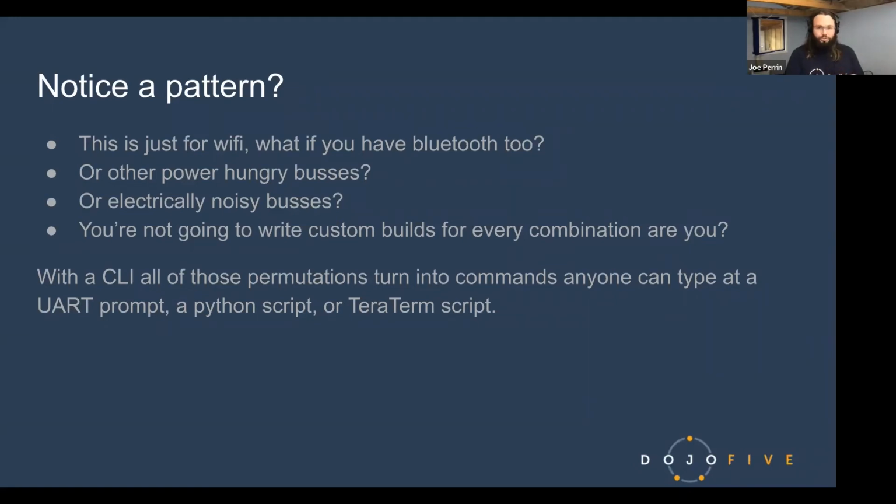If it's a separate Bluetooth transceiver, you can turn that on in max transmit. You can turn the GPS on and see if you've got coexistence issues, right? And when your systems guys are doing things like FCC regulatory tests, they're going to run all those things. That max power test might start out like, okay, we've got the Wi-Fi driver working, we'll do max power Wi-Fi. Hey, we got the Bluetooth driver working, or we got the GPS driver working, we'll add those to the max power.